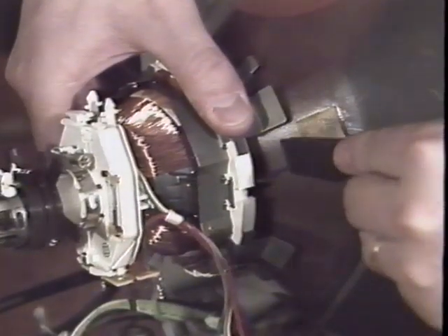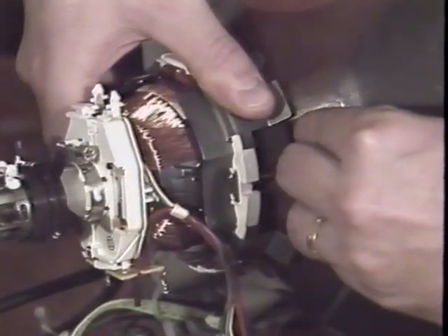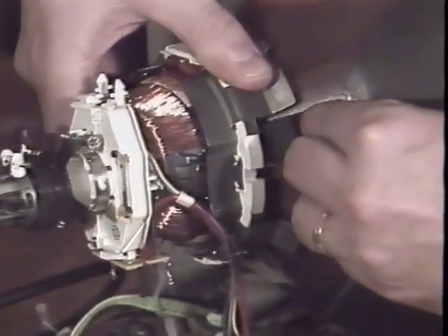When the crossing near the corners is minimal, insert the bottom wedge and one of the top wedges to secure the yoke's vertical position. Next, see if any of the beams appear offset from the others in the corners of the screen. If so, tilt the yoke from left to right to minimize the offset.